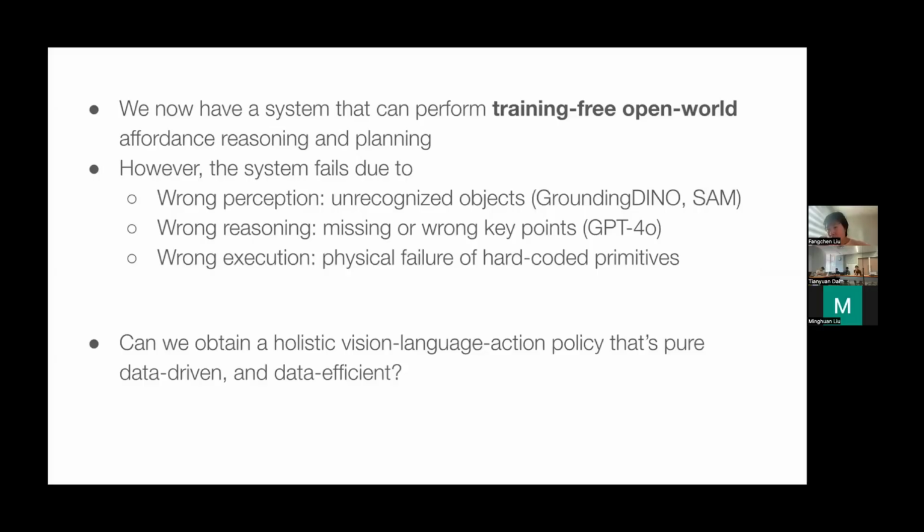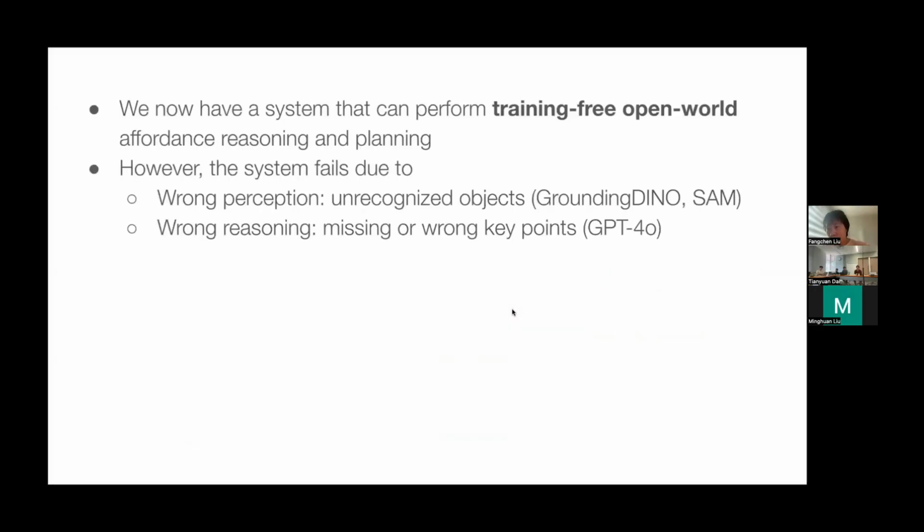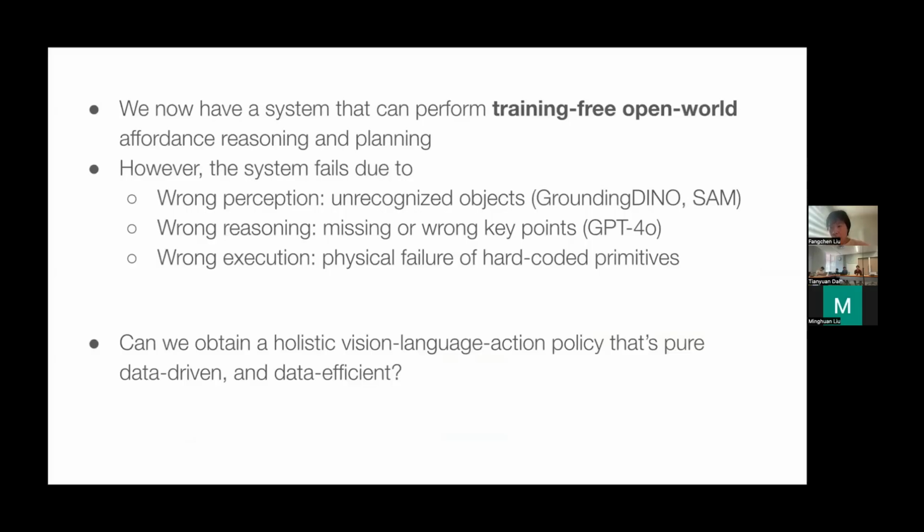Okay, thank you. Because it's only able to give you something on 2D images. So for waypoints, it's in free space, so it has ambiguity in 3D. That's why we have to hard code heights for different tasks. If it's a tabletop task, we just hard code the tabletop height. But for all the other points on the objects, because we have the object depth, it's something we can read off the objects. But the waypoint needs a specified height. Yeah, that's a very good question.